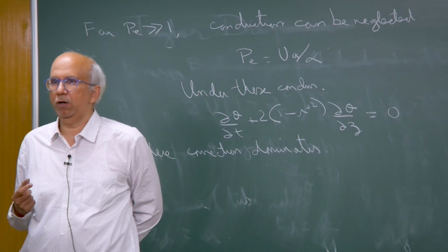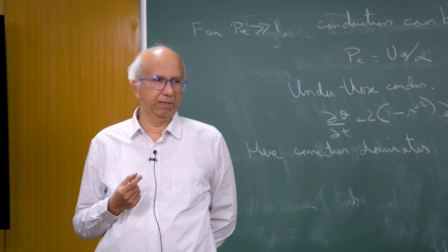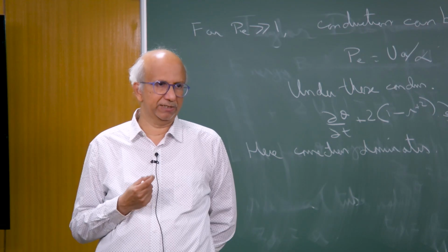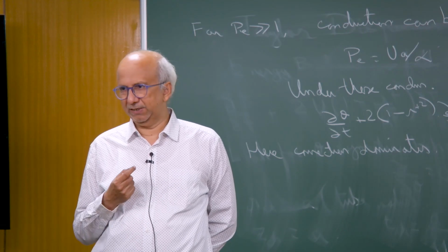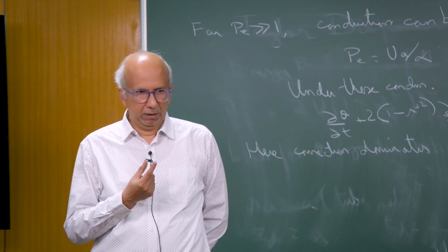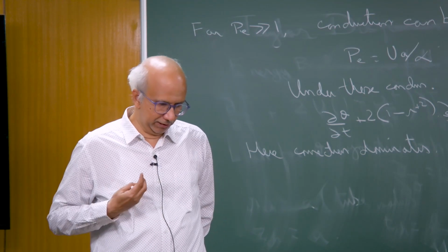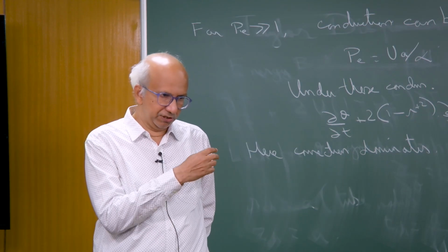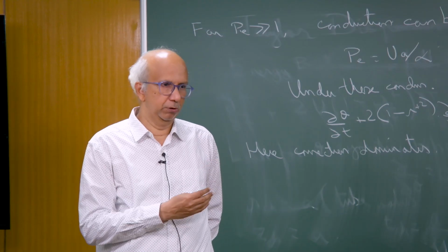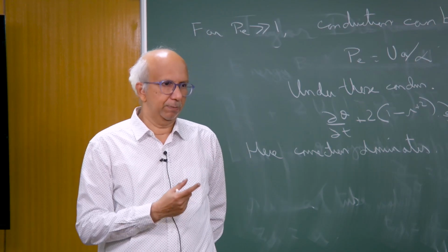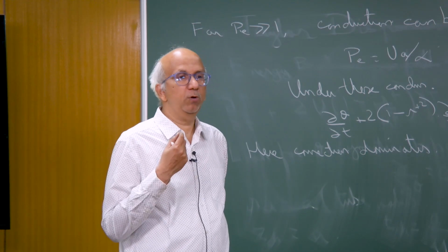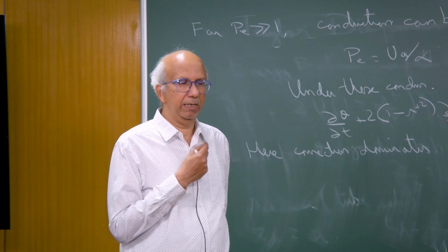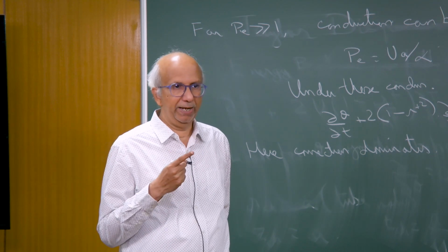Now, all of this is valid as long as this assumption that my choice for z characteristic being equal to A is correct. Now, z characteristic will be equal to A only for the initial portion, because when the liquid has just entered or the slug is just moving, the distance over which the slug has moved is A. And therefore, only for short times, the assumption of z characteristic being equal to A is going to be valid.